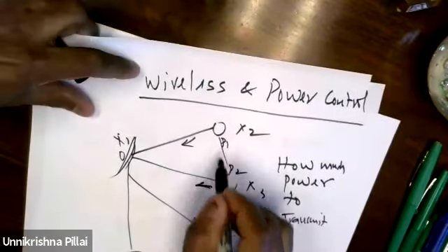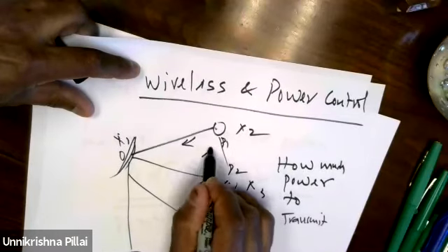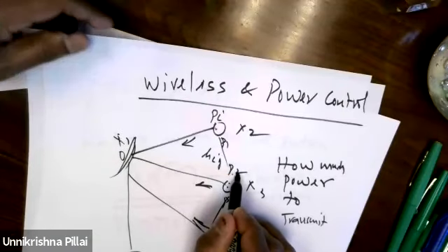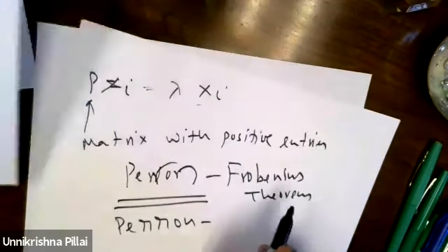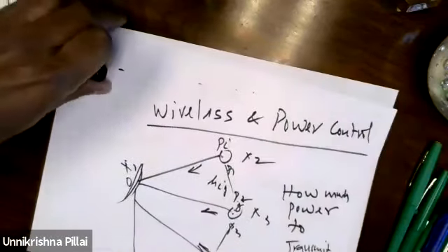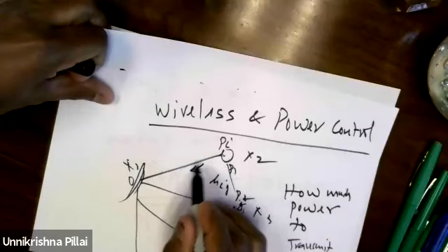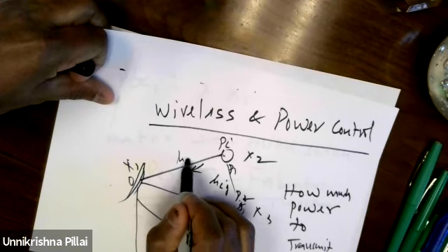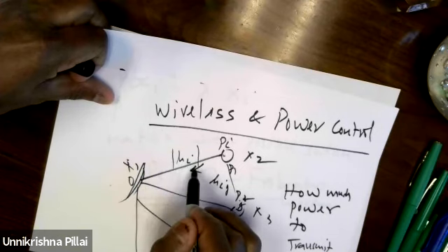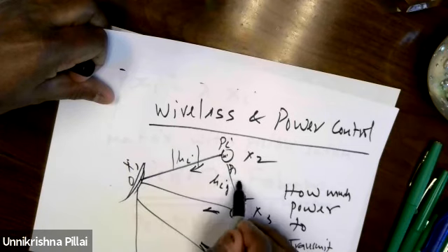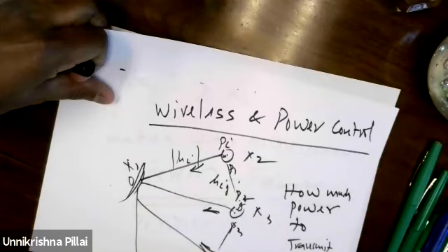Say you are talking to this guy. So there is Pi, and this is Pj. Most likely the way it goes, you know how it goes, the thing goes through the base station. I don't remember exactly, but let's call each of these Hi. Hi is the path loss towards the base station. Hij are the interferences to the other users.